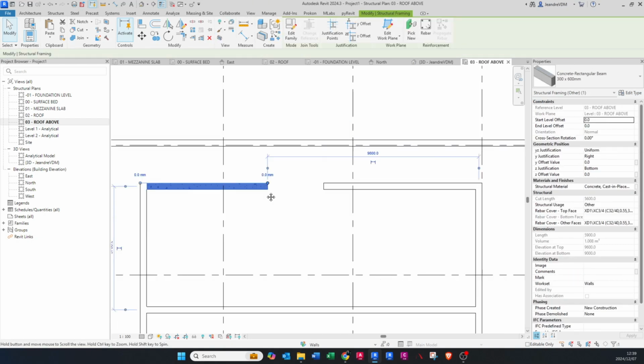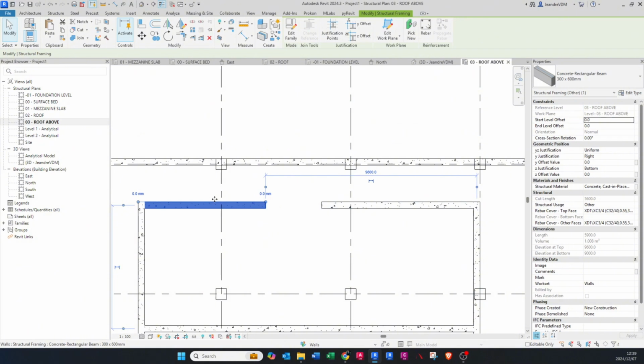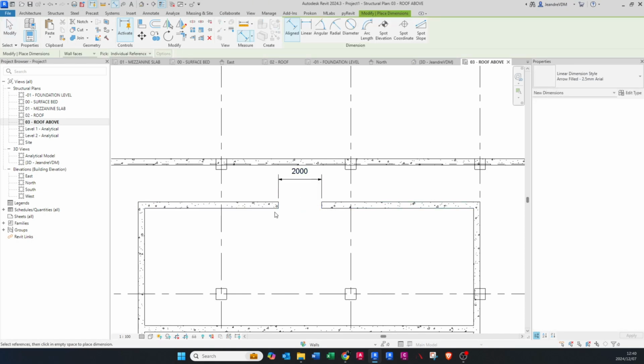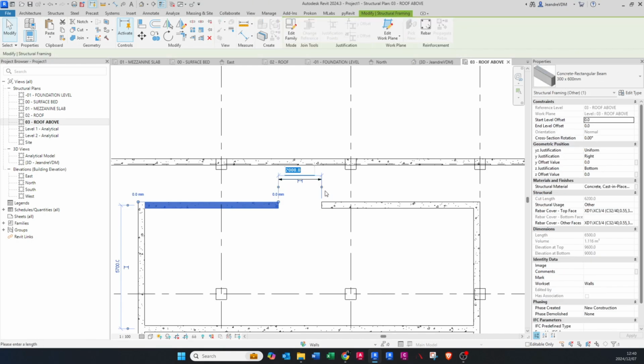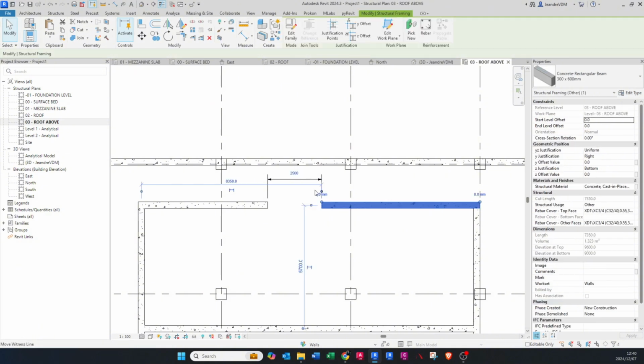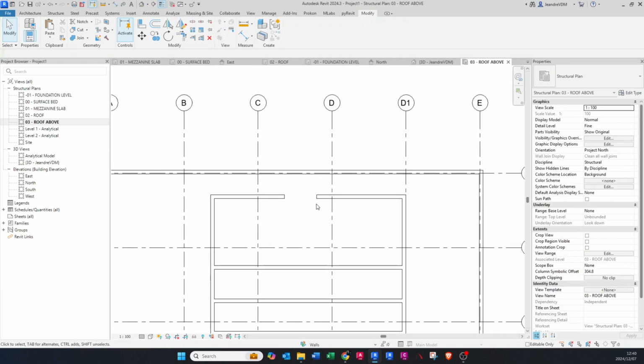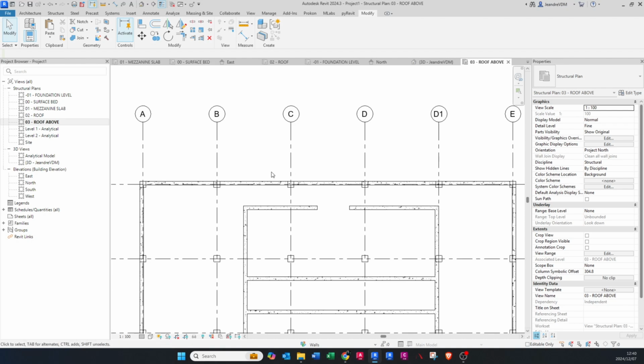And then if you want a certain size door, you click on that element and move it back to here, and let's say the door must be 2 meters wide. It brings in that. Or you can dimension it like that, click on it. I want to move it to 500. There we go. If you want to move that side, click this side and do the same. You see. Okay. Then you can also array elements.